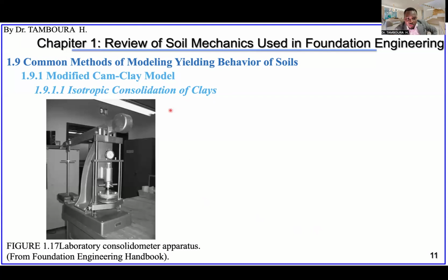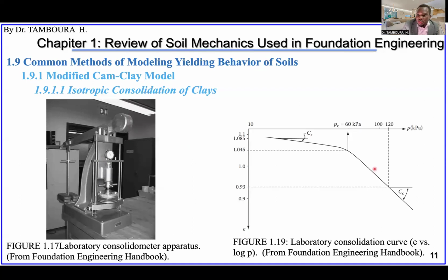This is, you remember this apparatus, the one-dimensional consolidation test for clay. I don't remember which video, the number of the video, but we did this before. Going with this to help us know the recompression and compression index.